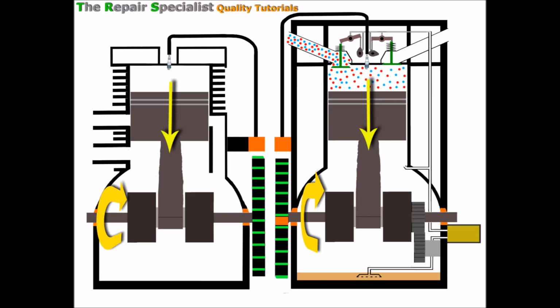So both pistons start to lower, and immediately there we can see on the 4-stroke that the piston has drawn in air and fuel above it. So it's both the drawing down of this piston, creating a suction and drawing the air and fuel in, and the opening of this valve allowing the flow of that air and fuel to actually come down the inlet manifold there into the cylinder above the piston. And so the opening of the inlet valve is timed perfectly with the induction of the air and fuel. And this is indeed referred to as the induction stroke, the stroke meaning the downward stroke of the piston. So we know the importance of the inlet valve opening on the induction stroke.